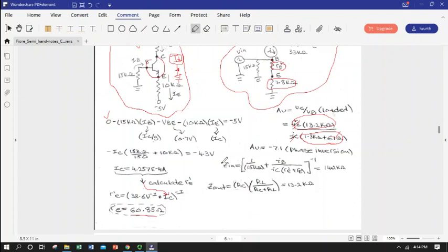We can also apply the formulas we just derived to define input and output resistance. So remember, in the input, we've got the base resistor in parallel with our collector current adjusted expression for the impedance path looking into the base and down to ground, which is this term, V in base, and the whole thing to the -1 because it's a parallel combo.